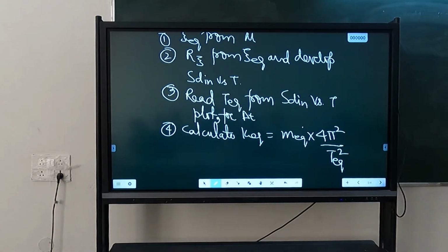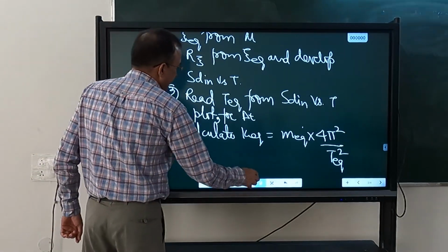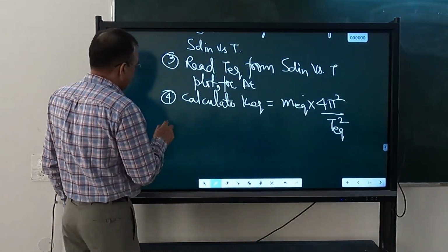Suppose I have a 10-story building. I have to convert that 10-story building into equivalent single degree freedom system. How do we convert into equivalent single degree freedom system? The mass of the 10-story building divided by alpha 1, and alpha 1 is summation mi phi i whole square divided by summation mi phi i square. Modal mass. Equivalent single degree freedom is the modal mass as per that particular motion which you have considered. So this gives you K equivalent.